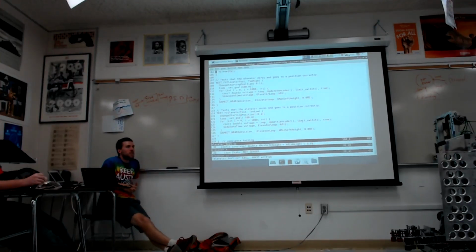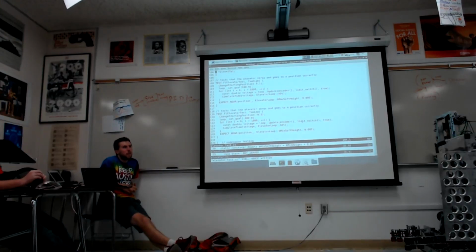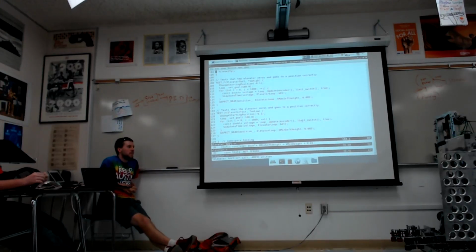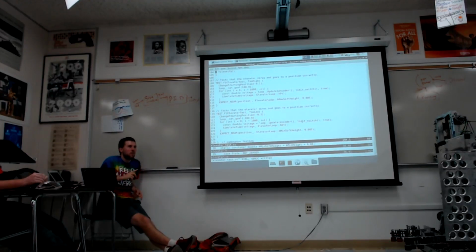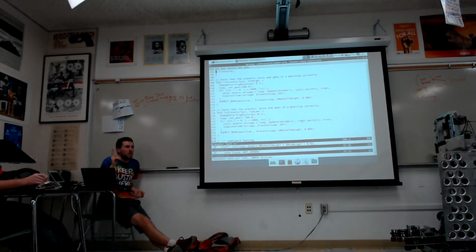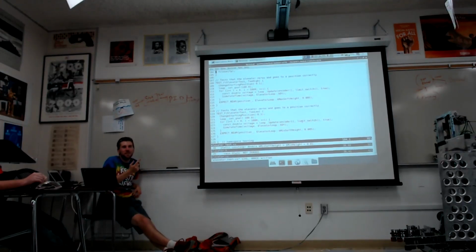So the first thing we're going to do is confirm that all of our sensors and motors work as we expect. Because one of the most common things is if the motor is plugged in backwards, so it goes down when you ask it to go up, you're not going to go very well. Other failure modes, so that's the first one. And then the next thing we're going to do is turn everything really far down. So if you start with like 2 volts, 0.1 PWM, it's barely going to break friction. So we should be able to tell if it's doing something reasonable at that point.